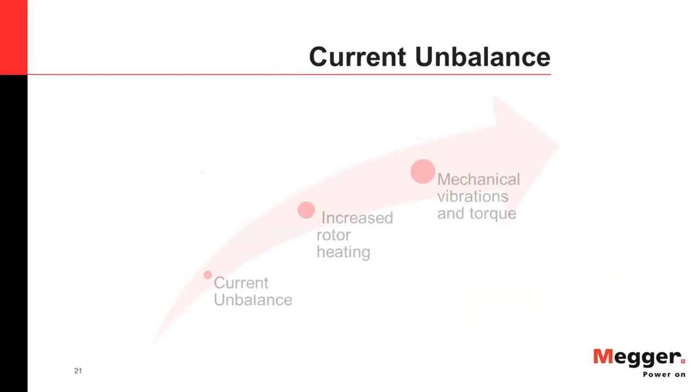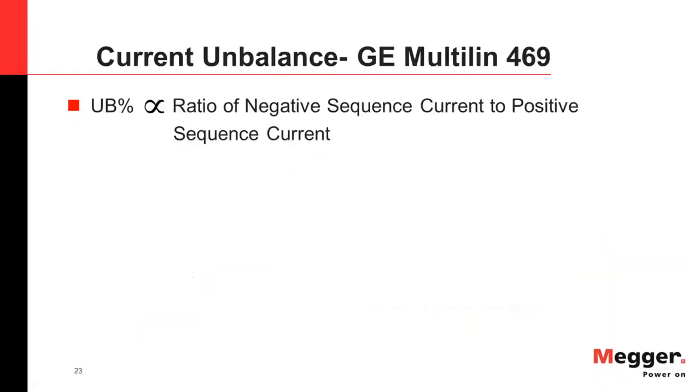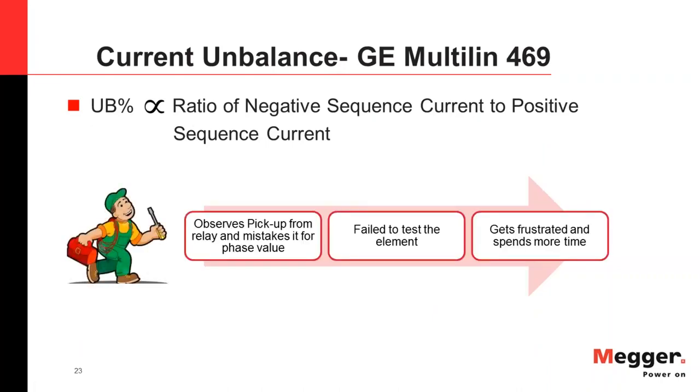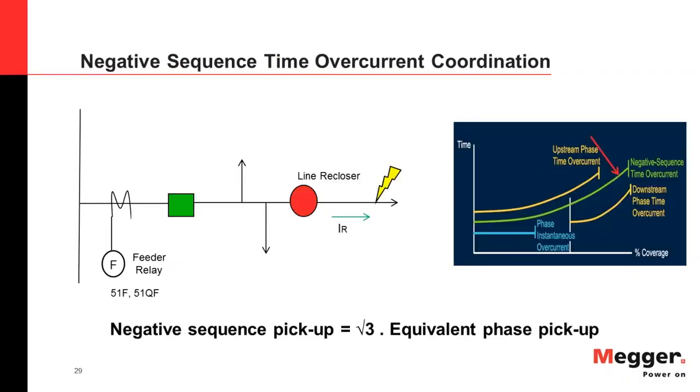The one before, I'm sorry. So the equivalent phase time overcurrent curve is basically what it is when you have just a phase B current flowing. But in case of the normal setting for the phase overcurrent, you have all three phases, and for a line-to-line fault, you have a high value because your B and C phases both are giving the current.